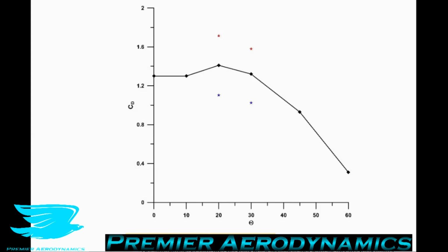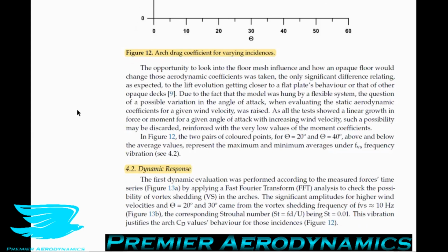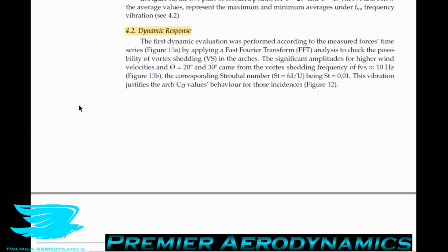The bridge deck that we saw before, we didn't test that high. Like you can see, they only went to 8 degrees. So in that range as well, the arch here is insensitive to the angle of attack range. So we can't really comment on whether the bridge itself is more sensitive to angles of attack or less sensitive to angles of attack compared to the arch itself. Either way, the drag coefficients are very interesting for either one.